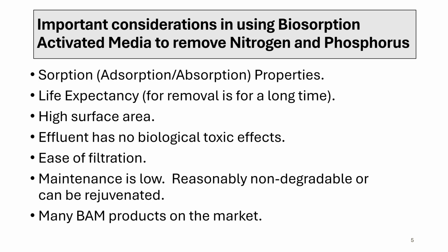It is also important to ensure that the effluent leaving the system has no biological toxic effects, meaning the media itself should not introduce harmful substances into the treated water. From an operational standpoint, ease of filtration matters as well, since the media needs to work within your filtration system without causing complications.